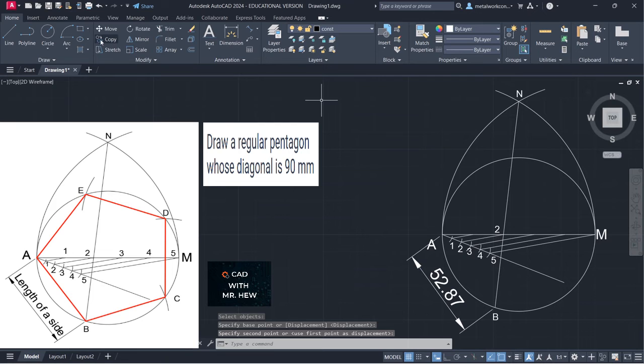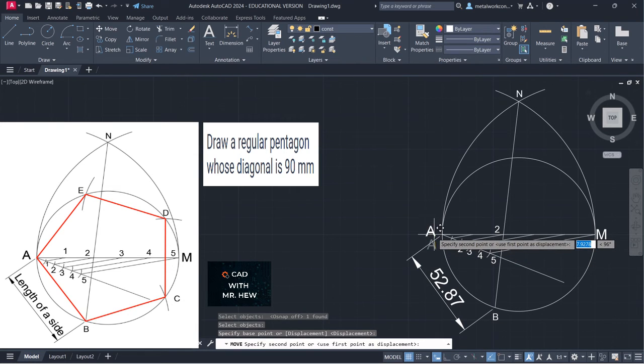We need to turn off object snap. So we're going to move, turn off object snap. Select the object, press enter, base point, any point. Would be a base point. All right, there it is. And the M is a little bit too close. We're going to move the M. Enter, select the thing, base point. Good, a little bit better.